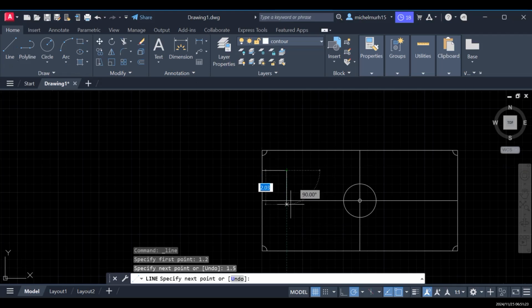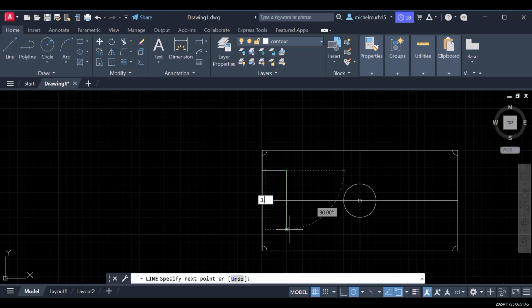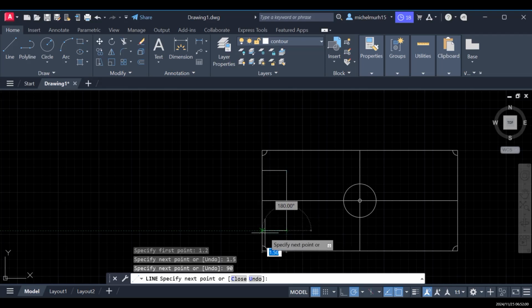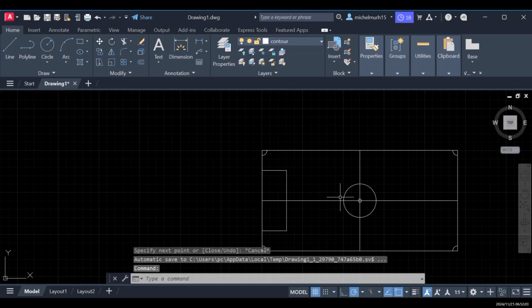And you can see here, from this point to the middle center, hit this line. The space is 1.8, so 1.8 times 2 is 3.6, right? So we can just scroll down and type 3.6. Just make sure it's 90 degrees. To do that, click on tab and change it. If it's not 90, you change it to 90, but mine was 90 since before. So I'm just showing you. Then I'm gonna link it in here. Okay, now we have the penalty area.